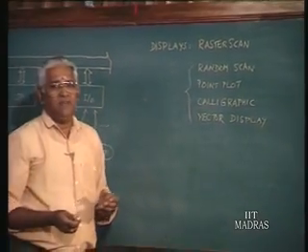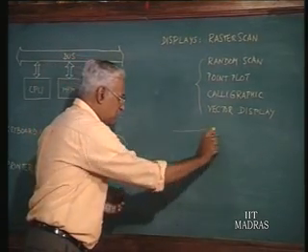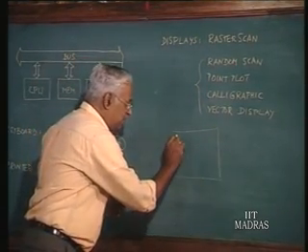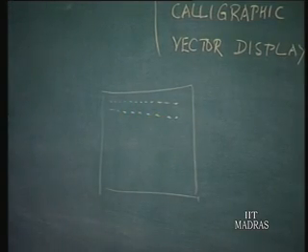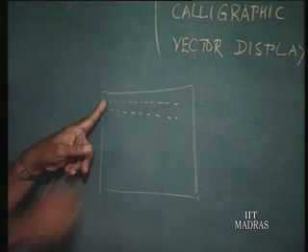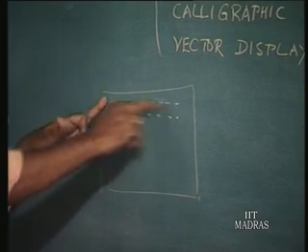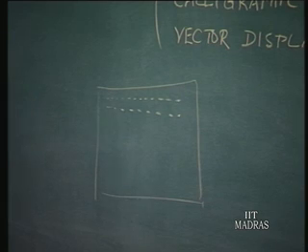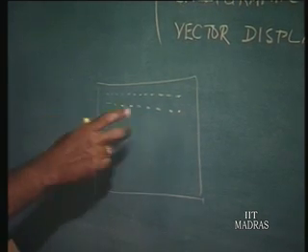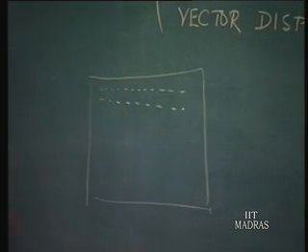and that is what we have even in TV. Okay. What is a raster scan? If you take the screen, the display is formed with scanning across the screen in this particular manner, right, that is from one end to another, and the time taken for this particular beam to move from one end to the other end will be about 52 microseconds, and then for it to go back will be 12 microseconds. Okay. Now, within this 52 microseconds, one line of information, it may even correspond to one dot. That particular thing will be scanned.